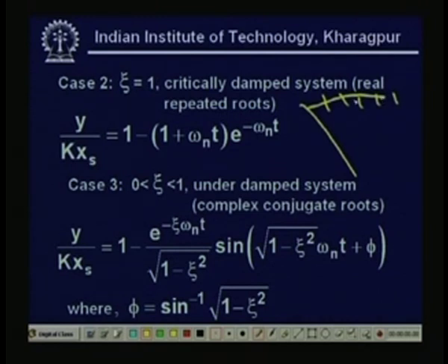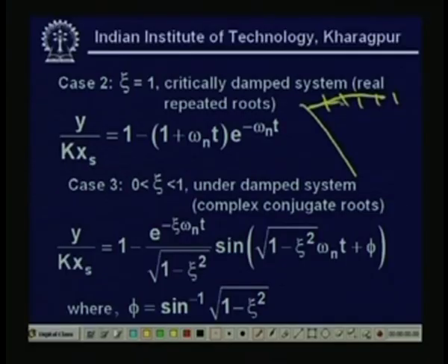That is where you take the measurement. If you take the reading whenever it is crossing, you will be wrong, because that is overshoot. When it comes back to the original position, that is the actual reading, because we have done the overshoot purposefully. It is an underdamped system and the value of the damping coefficient is 0.6 to 0.7.